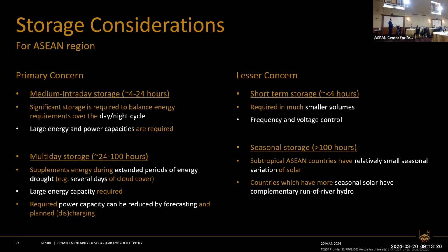There are several different types of storage. You can divide them by how long you are storing the energy for. So not how long does the energy last, but how long are you storing it for. For ASEAN, the most important things are medium to intraday. That is, you're storing energy for 4 to 24 hours before you use it. This is for day-night cycling of solar primarily. And multi-day storage. This is more than one day, up to about 4 or 5 days storage before you use the energy.